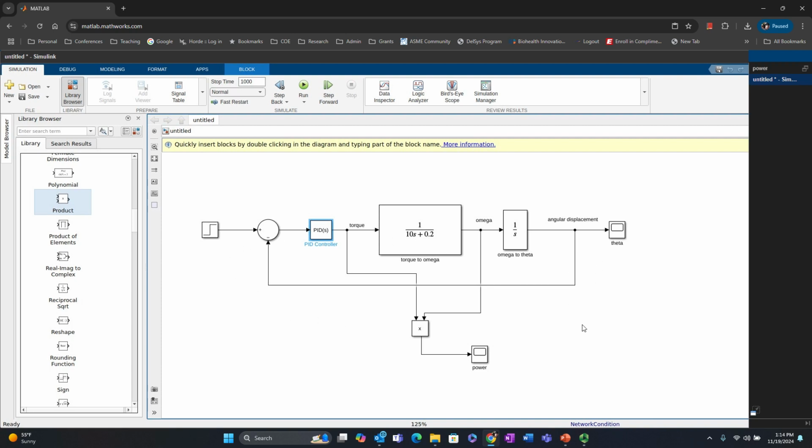So in the simulation environment, you may not realize that, because the simulation doesn't know what actuator you're using, but you should be aware of the limitations of the actuator that you're using if you have already one, or you should use simulations of this type to figure out what power levels are needed to complete the operation so that you can go and shop for a particular actuator that will handle those power levels. And that was the main goal of this demonstration.